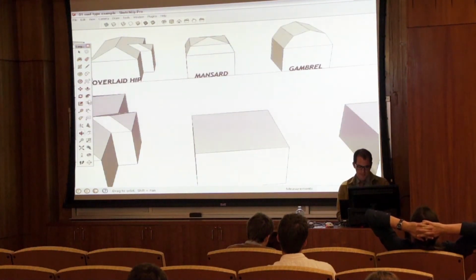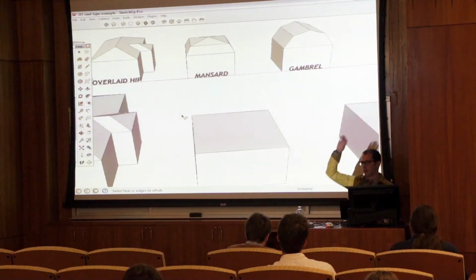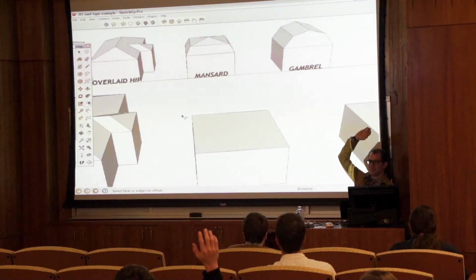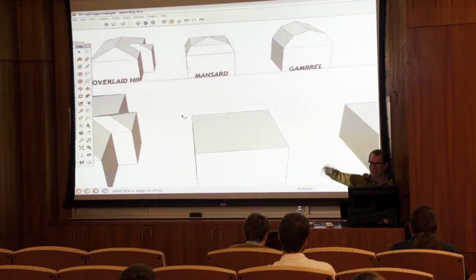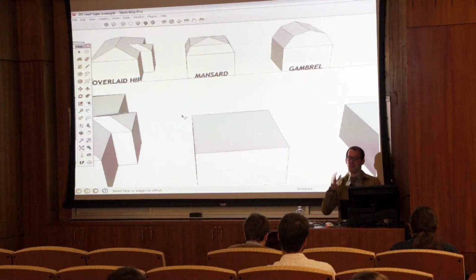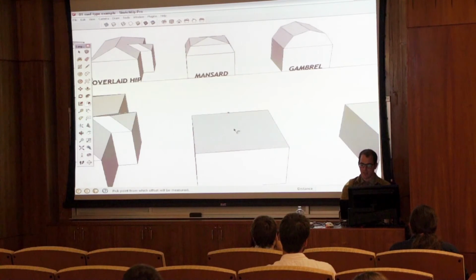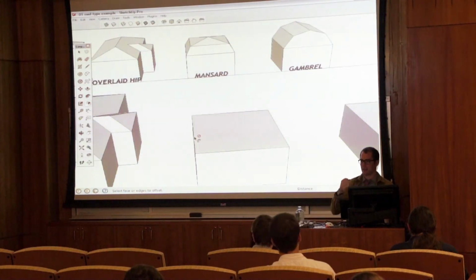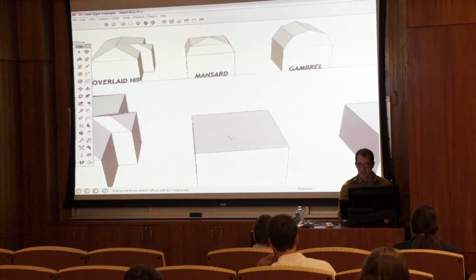So to use offset, and I mentioned this in the advanced class, but anybody use AutoCAD? A couple. Okay. Use the offset tool in AutoCAD? It's not like the offset tool in AutoCAD. In AutoCAD, you click on the actual line and then offset left or right. In SketchUp, however, it recognizes the face and not the edge. If you go to click on an edge, you get a warning sign. You can't offset a specific edge. Well, you can, you just have to pre-select it. In this case, you can offset the face here.